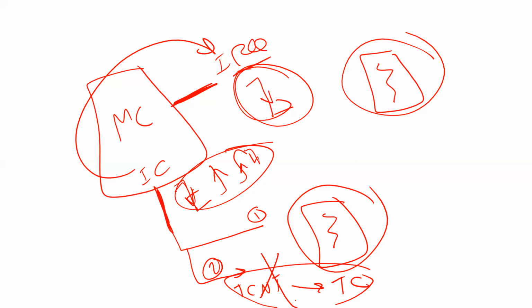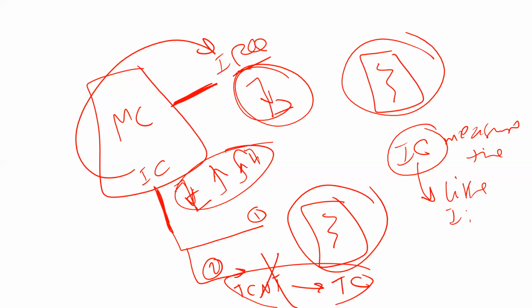So now I wanted to say something very interesting. Now I told you input capture is used if you want to measure time. Yeah, that's true. If you want to measure time, use input capture. I want to add something to it now. Also, input capture can be used like IRQ. Yes, as you see here.